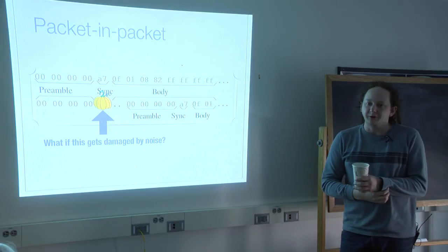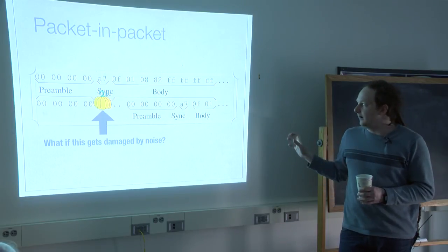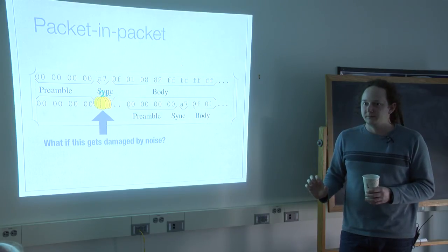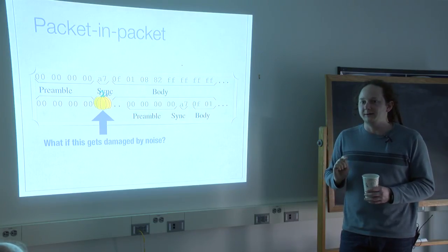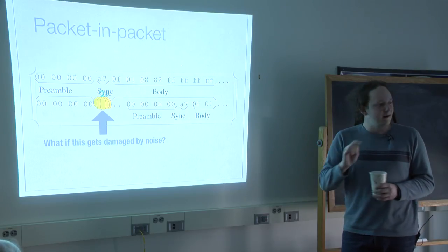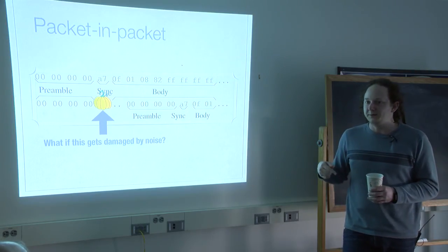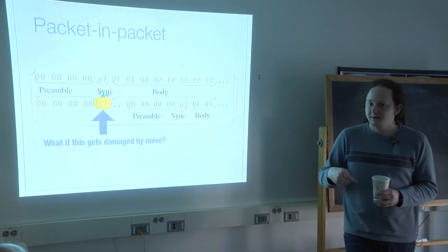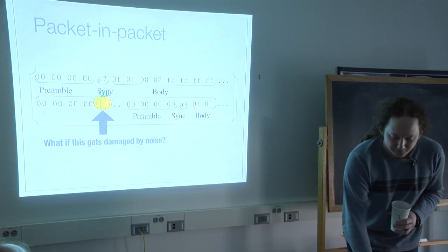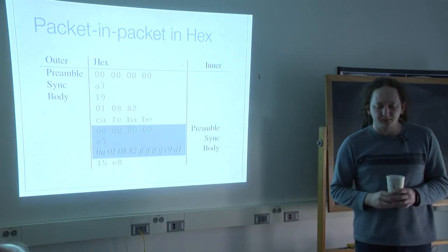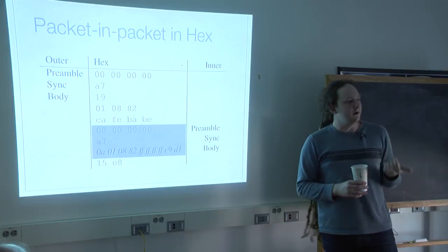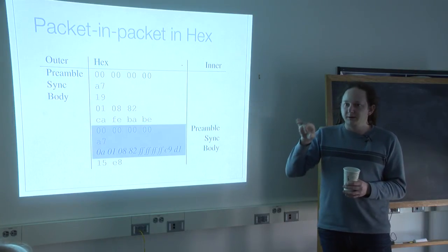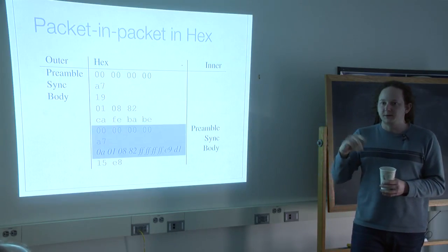So in this way, we can inject a layer 1 frame in the raw, given control of only layer 7 data. So I can email a Wi-Fi beacon. And it doesn't matter that a Wi-Fi beacon can't be encoded in TCP/IP. It doesn't matter that it can't be encoded in email. I can send it over UDP if I like. And as long as I can get it relayed over the air, and as long as I know what the radio symbols will be produced by it on the air, I can then adjust those symbols to produce the sequence of data that I like.